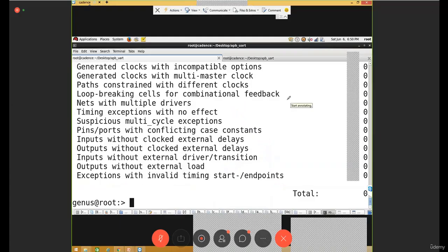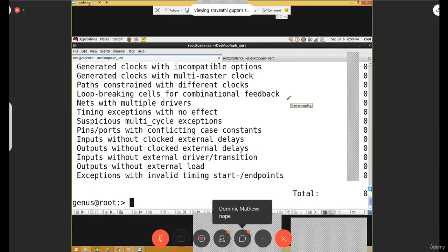So now here, once the complete process is done, that means you have done 3 steps of implementation, that is translation, mapping, and optimization. You need to generate some reports to move forward for this STA analysis or to move forward with the physical design analysis. Now, what are those reports? So the outputs of my synthesis is gate level netlist.